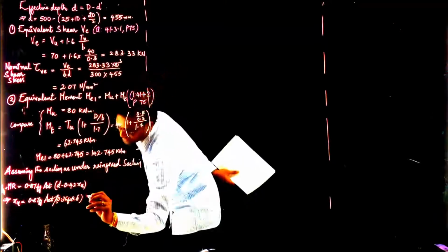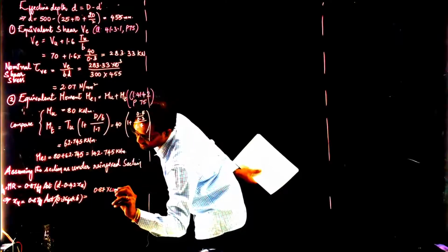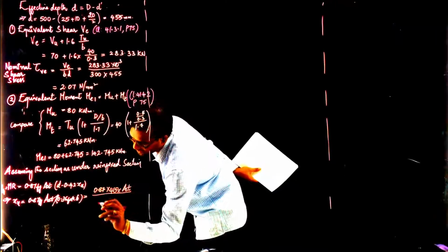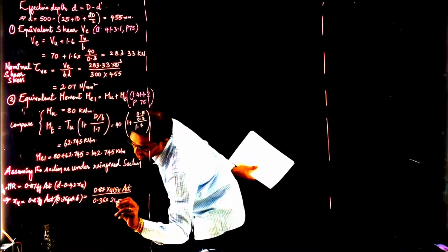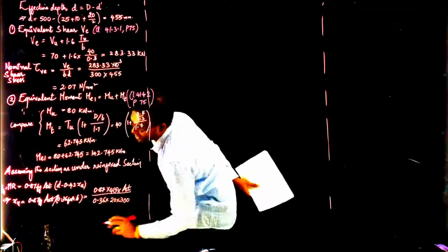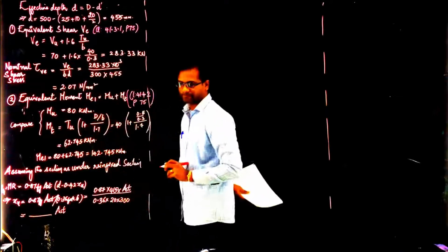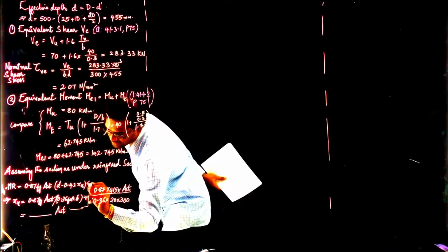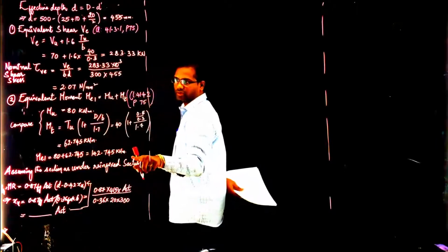Now back substituting, first calculate this. So this is given by 0.87 into 415 into AST, we need to calculate it, divided by 0.36, fck is 20, breadth is 300. Now you will get some value in terms of AST. Now back substitute this equation here, right? So MU1 is given by 142.745.